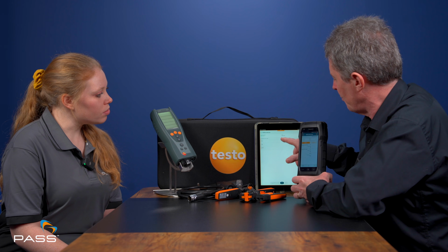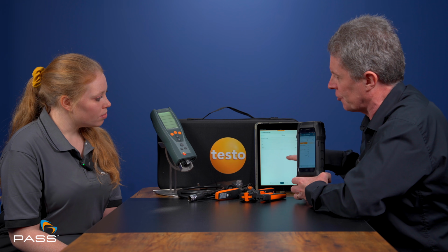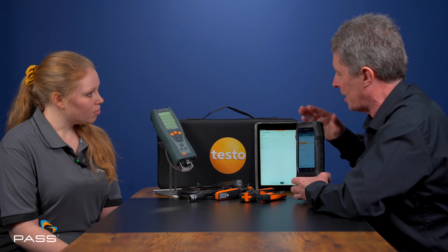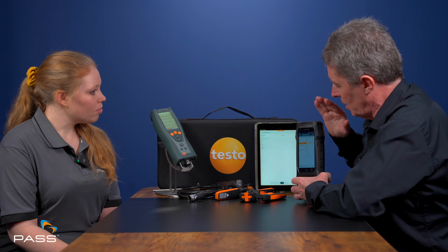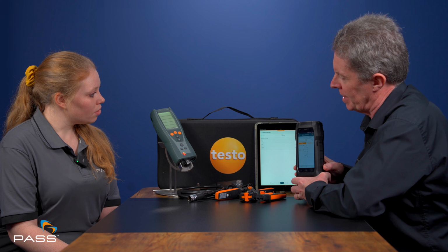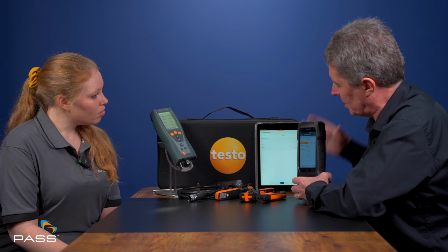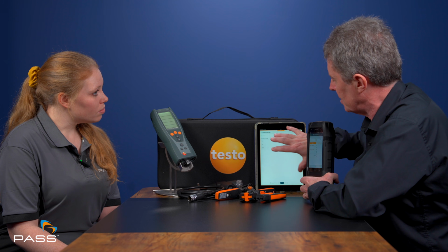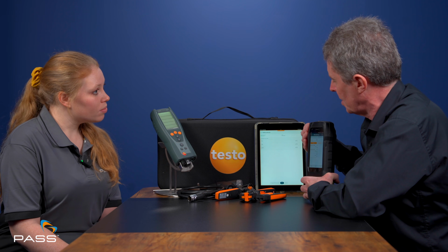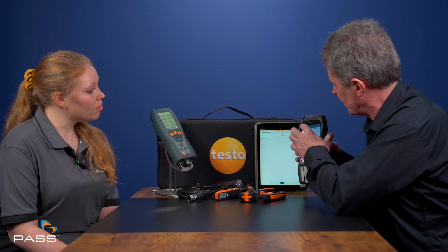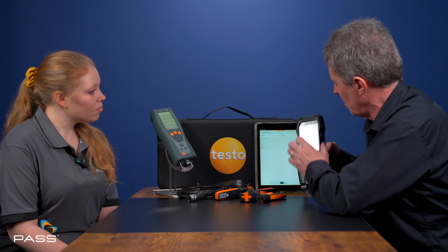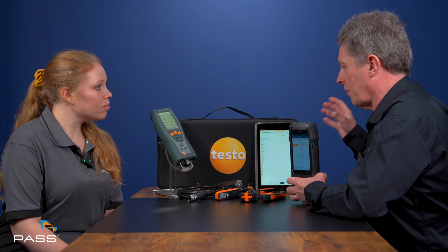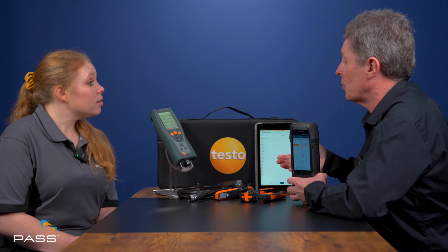And you can see here, we've got it connected to the app in what we call second screen mode. So this is the standard Testo Smart app. This is a fairly new update we brought out about 12 months ago. So the 300 can now talk to the app in what we call second screen. So what happens, this is always the master device, but this is giving you the option of having a second screen of the results. And where this becomes really useful is for something like a commercial engineer, where often the sampling point could be quite further away from where he's actually doing any adjustments, maybe on a burner.